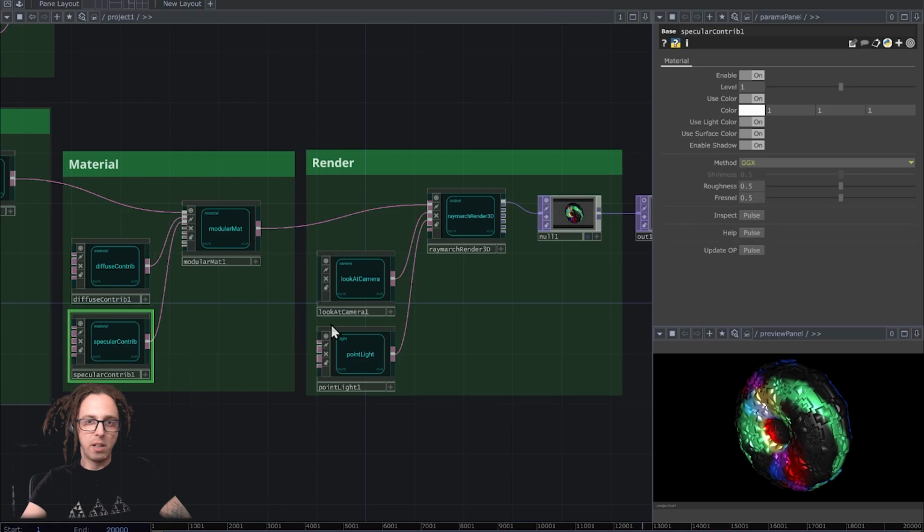And then on the specular, to spread out that highlighting, bring up the roughness to maybe 0.6. I kind of like to have a little bit of a shiny look on this one, but not super metallic looking. And then bring up Fresnel there to brighten things a bit, maybe 0.9.